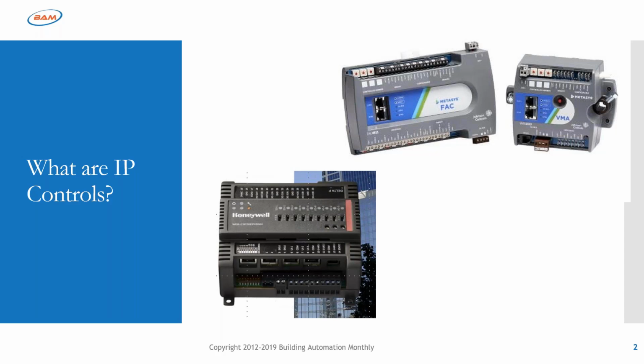Making sure you understand that stuff, and making sure they're not duplicated. Your BBMDs and BDTs are important. I think that's pretty much it. That's what I would focus on. It's not like LON where you have to have the CPs and SNVTs and NVs and all that jazz, and your SNVT types have to match, and if they mismatch, you're going to have issues. BACnet's much more forgiving on data type mismatches.